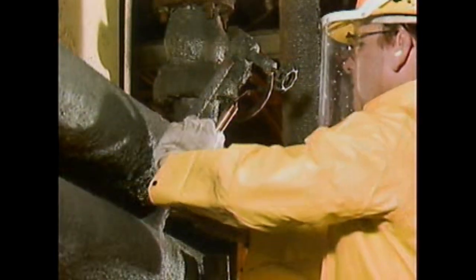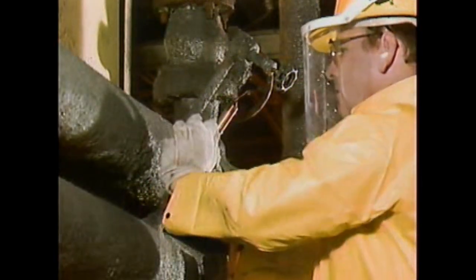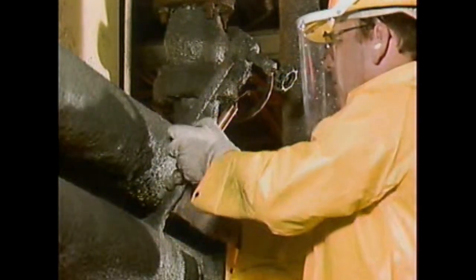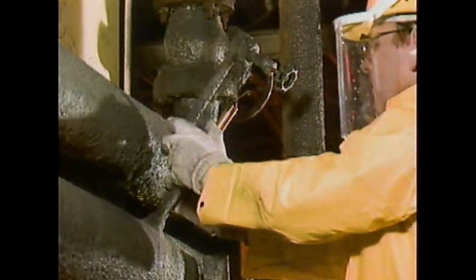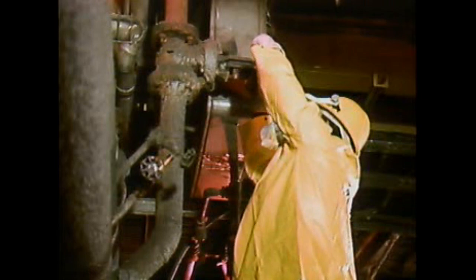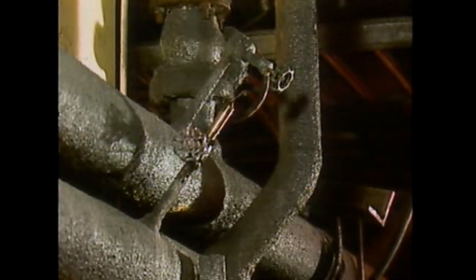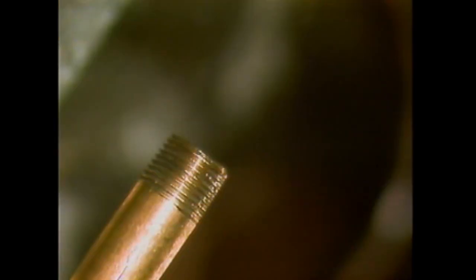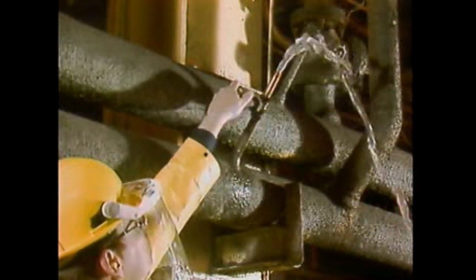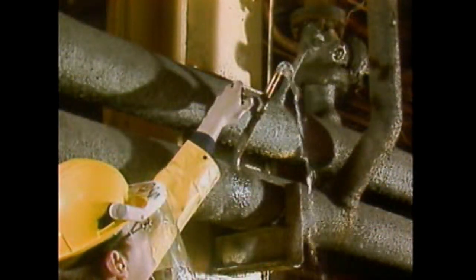Once he's sure that the drain valves are closed, the operator checks to make sure that the vent valves are open. In this system, as soon as the liquid is admitted, air will be purged through the vents. Next, he opens an isolation valve to allow liquid to flow into the system piping. Having the vent valves all the way open helps to purge the system of air and fill it with liquid quickly. However, as soon as liquid starts to come out of the vents, the operator partially closes the vent valves to minimize the amount of liquid that is lost.